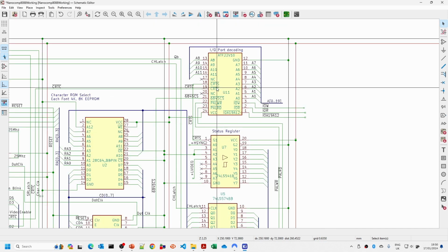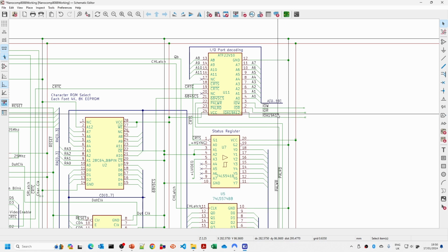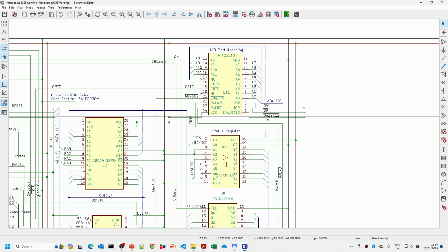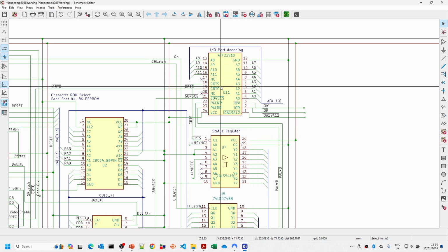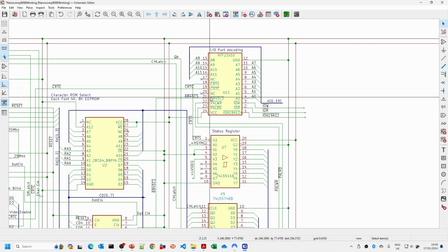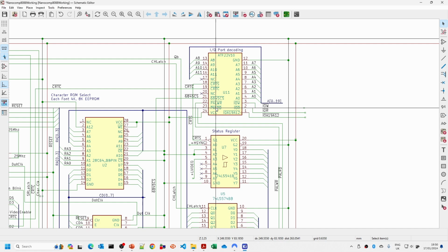The I/O port decoder takes a new signal that I've put on the main address decoder that just tells us whether or not we've got an I/O port, with the top address lines from A12 to A19 all 0, and all I/O addresses shouldn't be using that range. So this is just a signal that says we should have an I/O address with all the top address lines 0. And then we've got outputs here for the various CRT status control registers, the CRTC 6845 chip select, and then we need to do 2 separate signals for the palette video DAC, a write signal and a read signal.